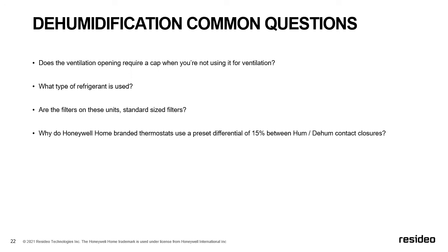We can have an offline conversation, but just know out of the box, if we're going to do both sequences with the onboard sensor, there's a deadband in between, similar to what we do if we're doing auto mode for temperature, where we want to have some space between driving heat or cool.